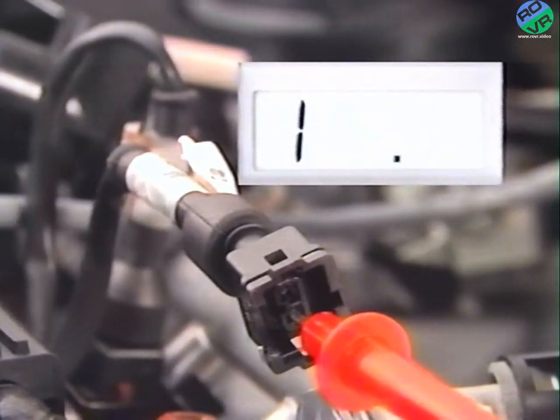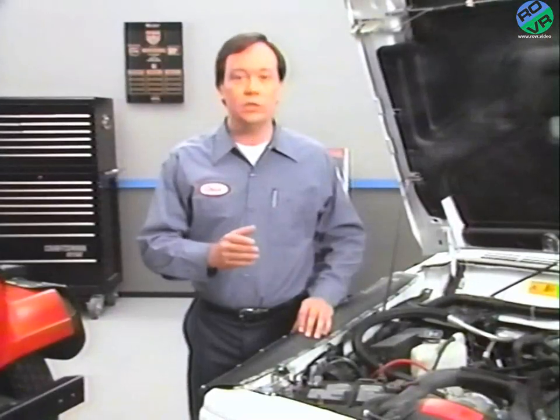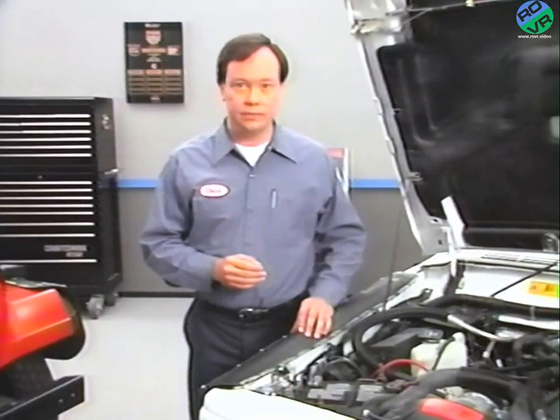If the resistance is above 10 ohms, there is an open in the wire. You'll need to repair the wire. If the resistance is less than 10 ohms, the problem lies in a faulty engine controller. Again, you'll need to replace the engine controller.